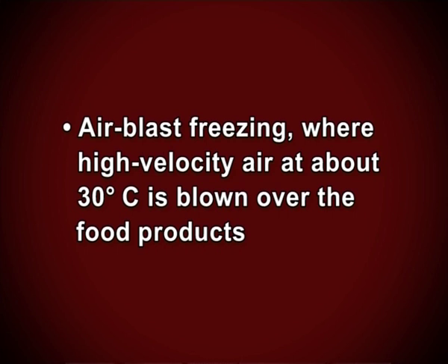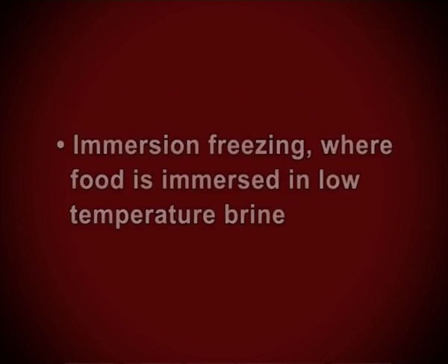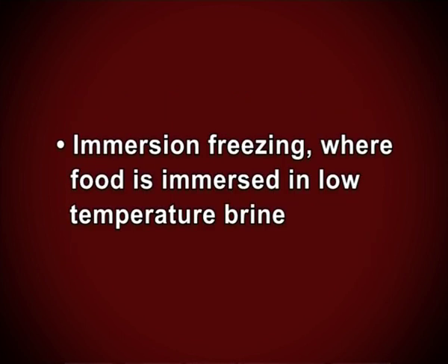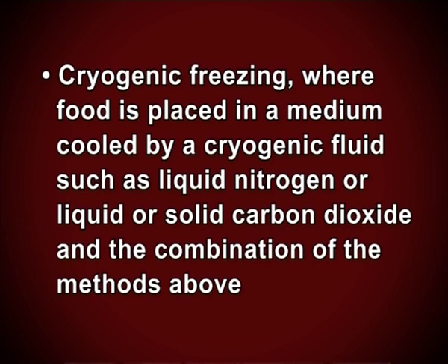Common freezing methods include air blast freezing, where high velocity air at about minus 30 degrees centigrade is blown over the food products. Contact freezing, where packaged or unpackaged food is placed on or between cold metal plates and cooled by conduction. Immersion freezing, where food is immersed in low-temperature brine. Cryogenic freezing, where food is placed in a medium cooled by a cryogenic fluid such as liquid nitrogen or liquid or solid carbon dioxide, and the combinations of the methods above.